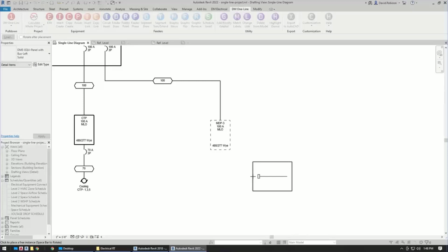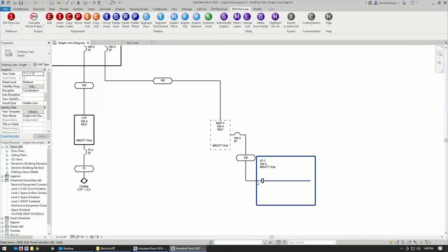So we say, Revit, I want to put in a family. Revit will put in the family for you, let you select a location. You put it in, and then Design Master says, okay, let's add those labels and let's resize it based upon how that project was put together. So you'll see that it made it a little bit bigger and it added that annotation tag as well. So that's what we're doing in the background to get all of this information in right.